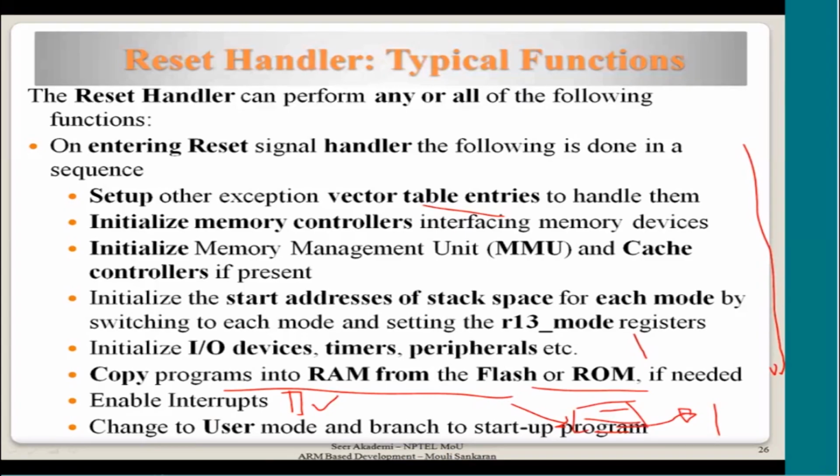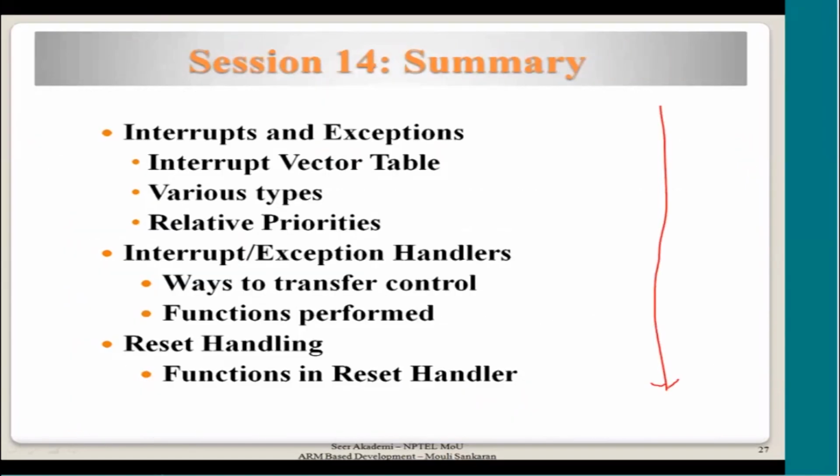If you understand this much, later on, if time permits, we will talk more about this. So we have come to the end of the class today. We have handled the most critical modules: what vector tables are, how the ISRs are enabled, how different banks are used for the vector table, what different instructions you can use to jump from the vector table to the ISR or handler, and what the functions handled by the reset are.